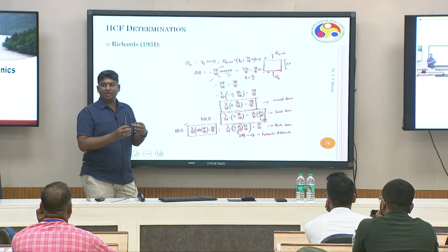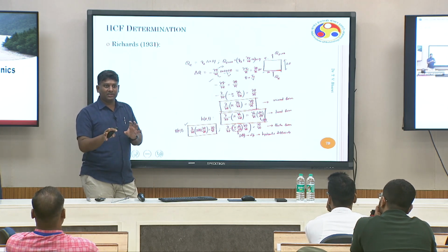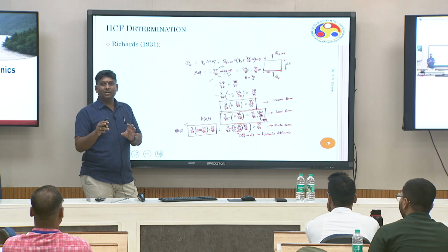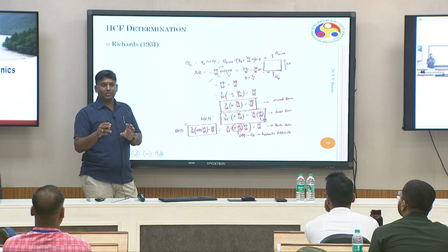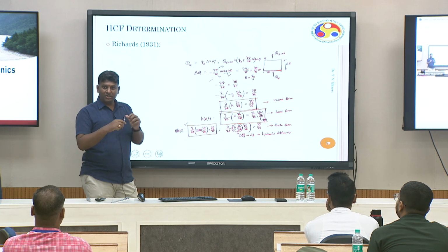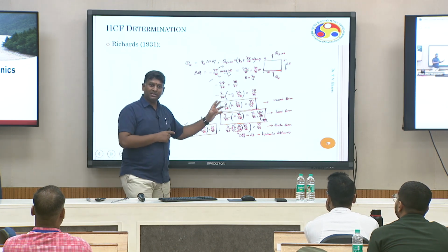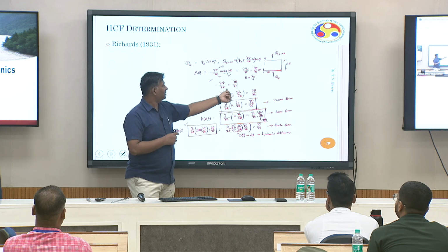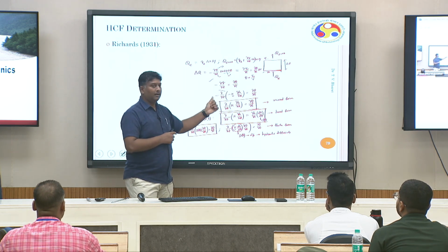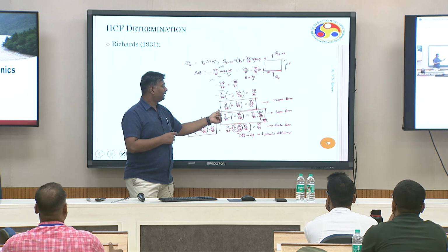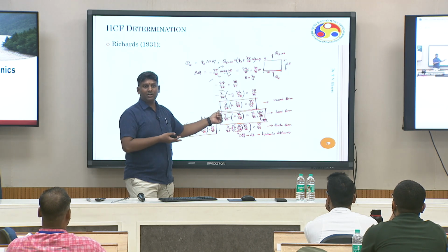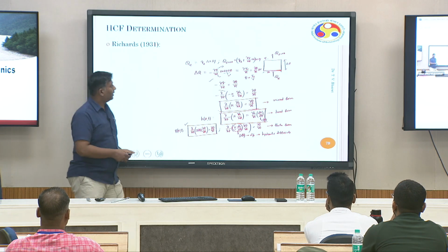There he plays with the state variables and then brings in those u values, etc. For that he uses one additional constitutive relationship, sigma dash equal to a function of e, to change the variables. Otherwise, if you don't change the variables, it is exactly the same. You have the mass conservation equation, then Darcy's law, and then you get the expression. That's it. That is your Richards equation. Fine?